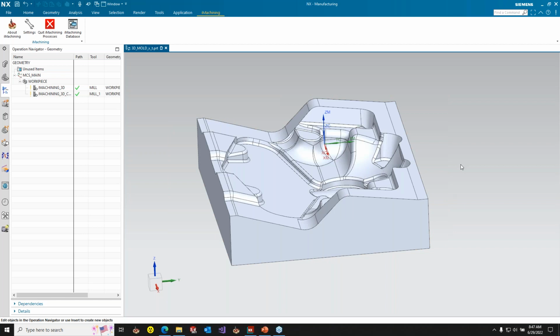In the algorithm, we are always trying to enter from the outside. The last thing the toolpath ever wants to do is helical enter, so we do everything we can not to helical enter.